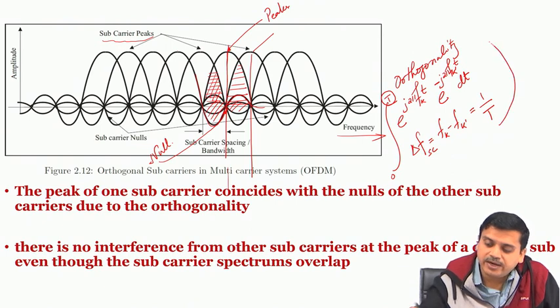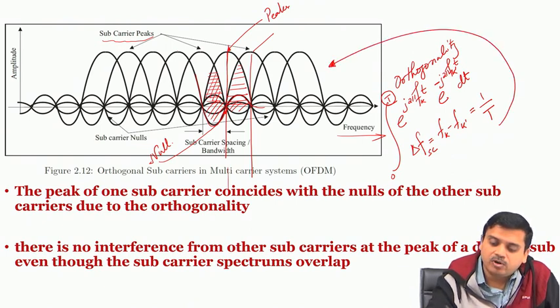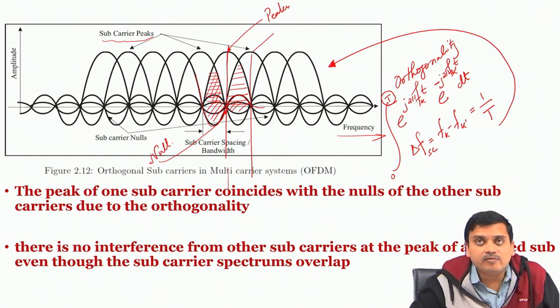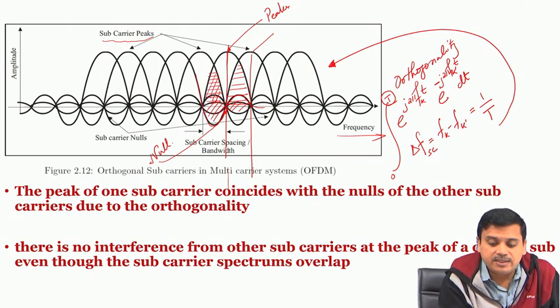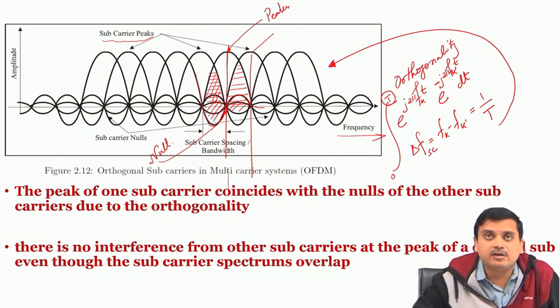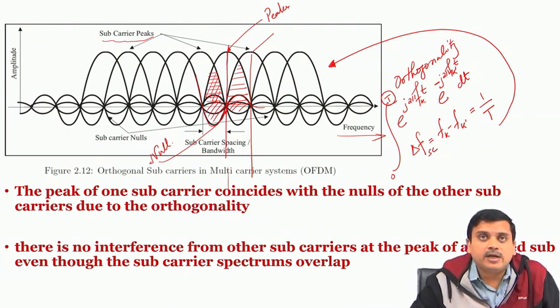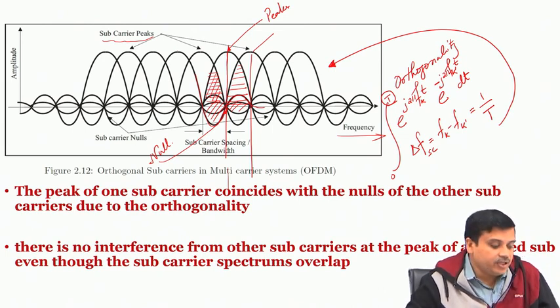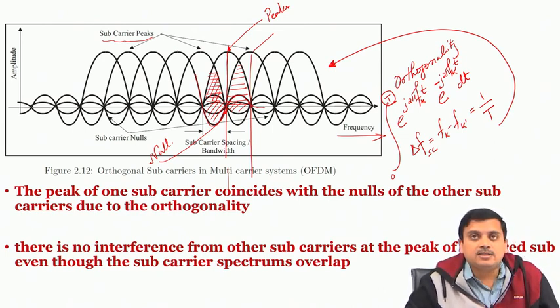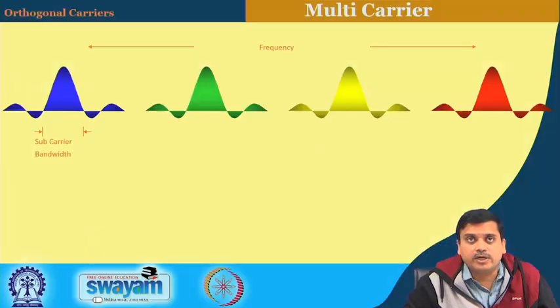So, we have used this criteria to get our signal. This would obviously mean that they are overlapping with each other, because the subcarrier bandwidth is spreading on both sides, whereas we are placing the subcarrier at half that interval. Although they are overlapping, by virtue of orthogonality, one is not getting any influence of any neighboring subcarriers. This way one can save a huge fraction of bandwidth, and this is the smallest spacing that one can think of. When we discussed MSK, we did say that the minimum term comes because of the smallest separation that is possible, and that is by virtue of orthogonality.